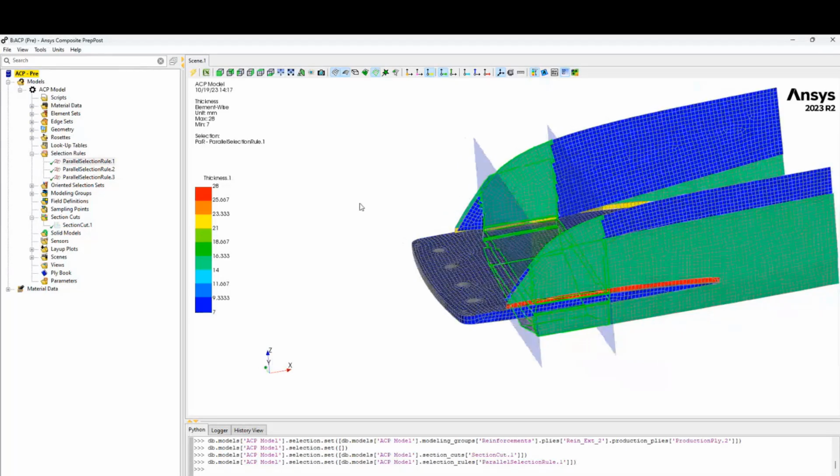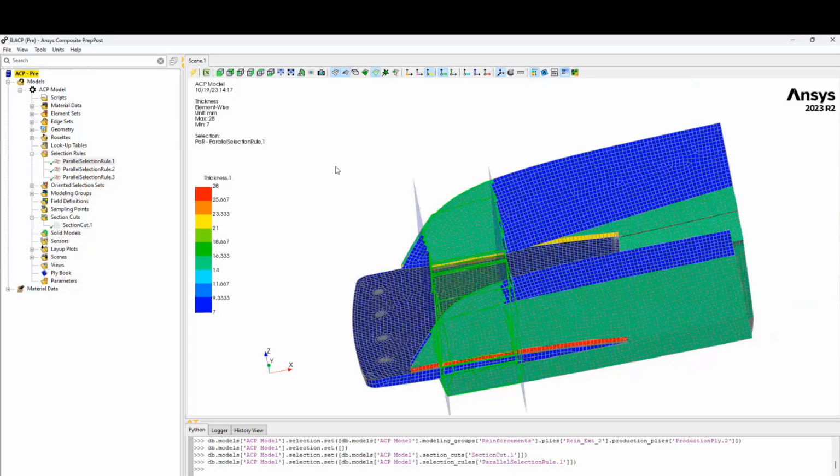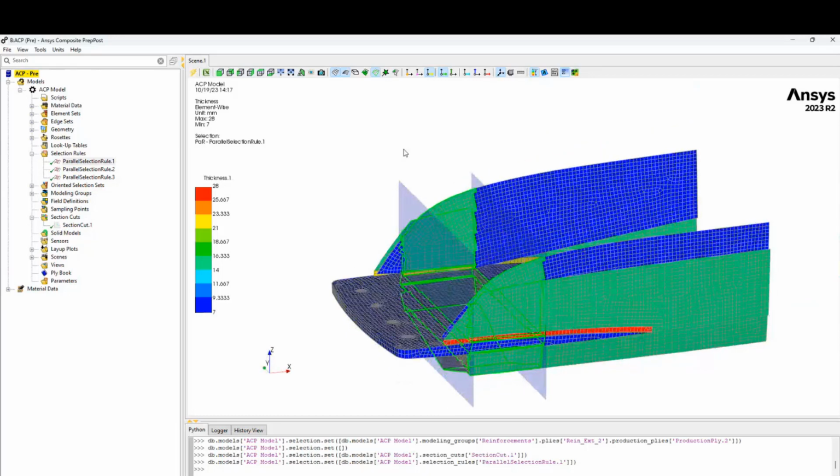And that's simply like a filter where we can define our composite structure. At the end, this is the way we use it. We define every layer, every orientation, every thickness, and that's all, in each section we want to model.